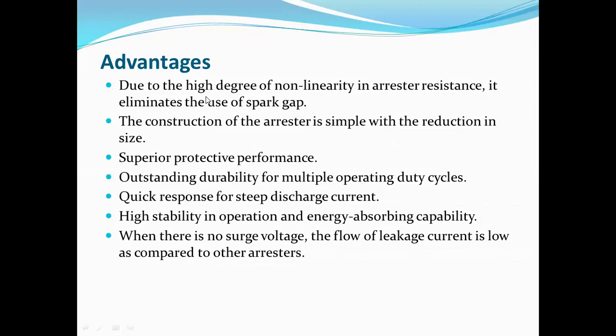for steep discharge current. Steep discharge current means if there is a highly intensive characteristic, then that arrestor gets operated immediately. It is stable in operation, and it has energy absorbing capacity.